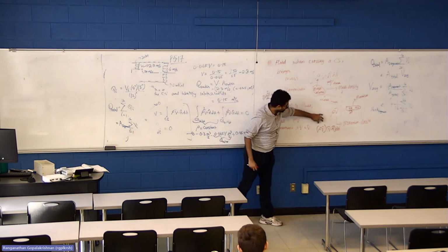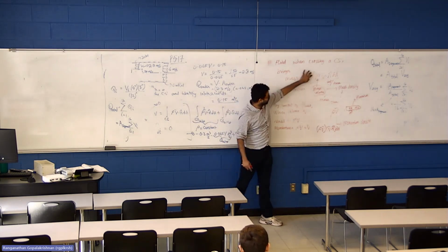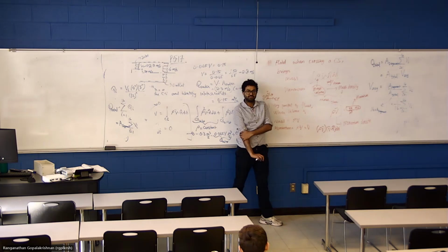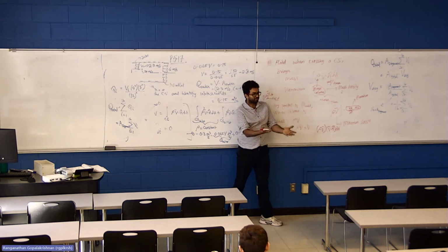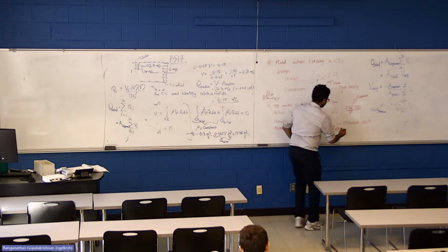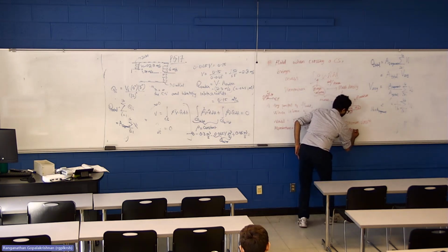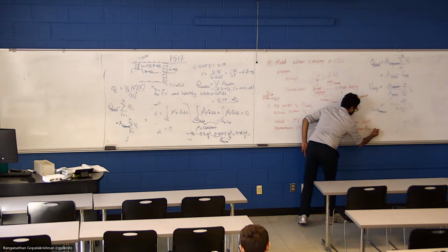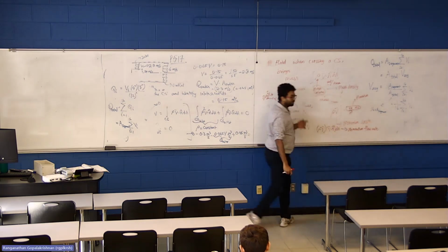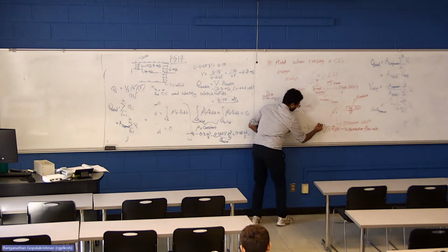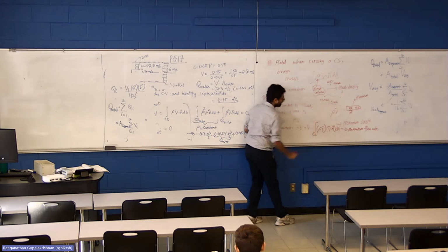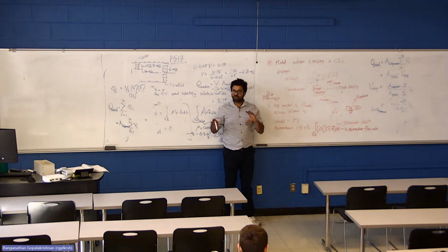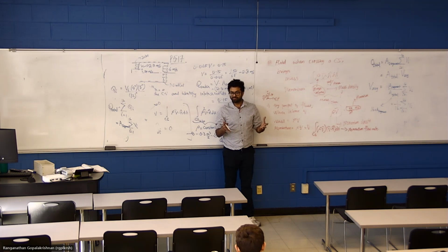What would be this quantity? What can we call it? Momentum flow, right? So this can be called momentum flow rate, and if you integrate this over the control surface area, you get the total amount of momentum that is entering this control volume.